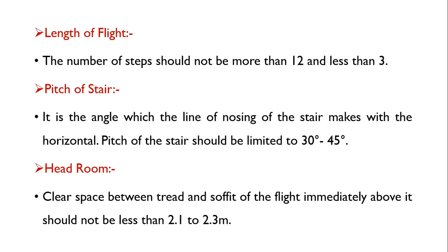Right? Headroom. Headroom is the clear space between the tread and the soffit of the flight immediately above it. It should not be less than 2.1 to 2.3 meter. Generally 2.2 meter is provided. Headroom means somebody or any person is moving on the staircase.